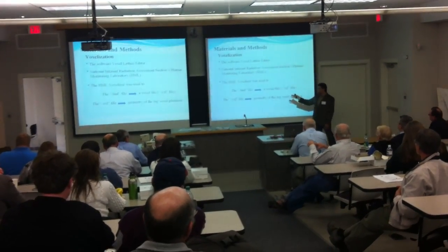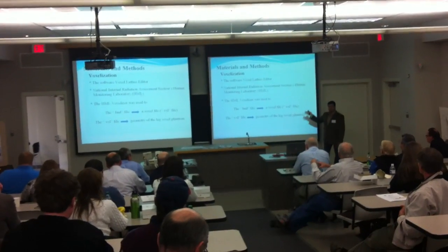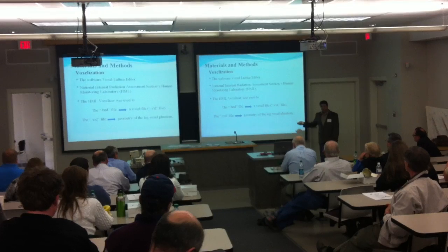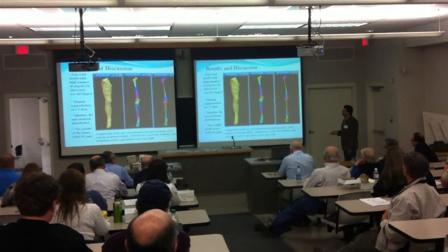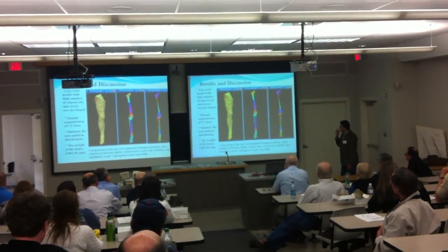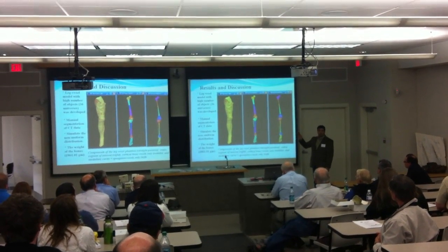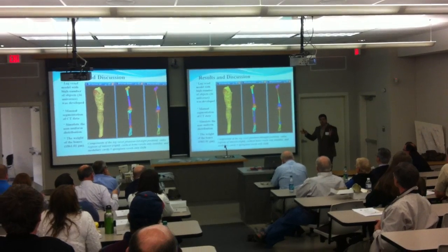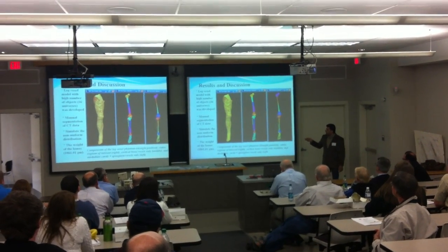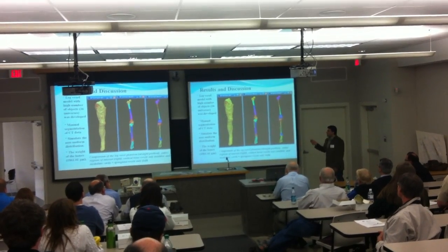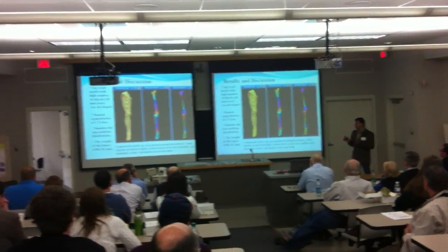The voxel file was then converted by the software to repeated structures to describe the geometry of the voxel model. As a result of this study, a new leg model with 36 objects plus the air object surrounding the phantom was developed. The phantom was created based on manual segmentation of CT images of a human cadaver leg.